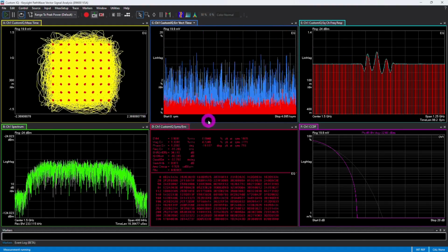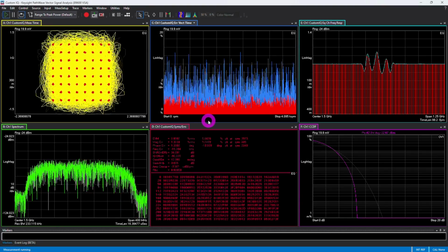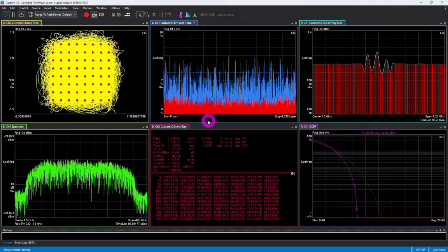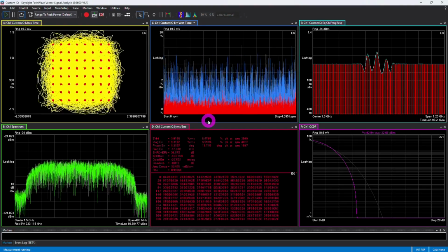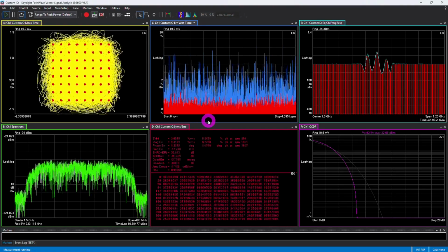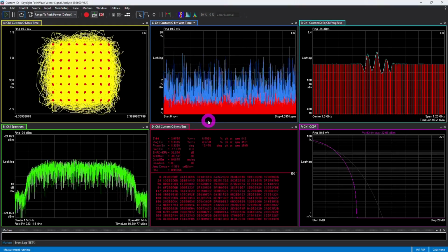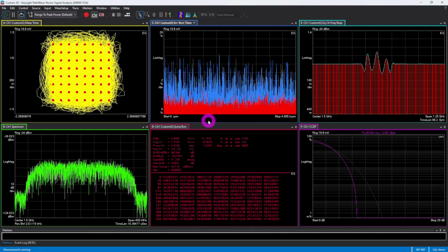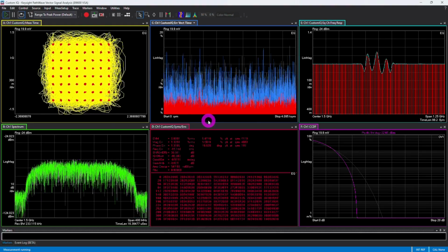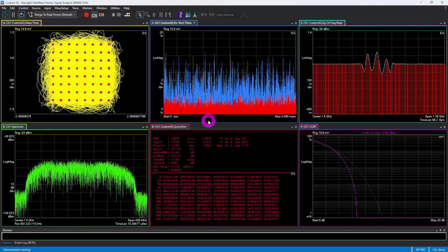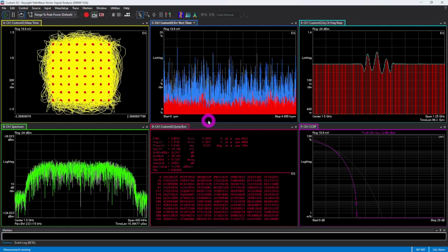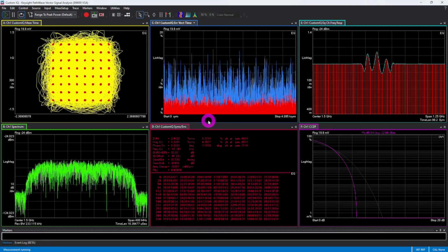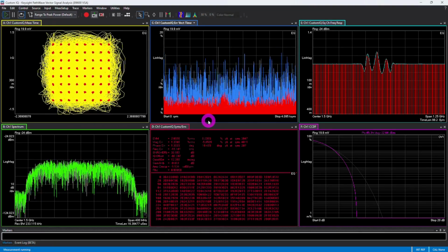So using the wideband IF, I can use any digitizer outside of the SM435 to digitize up to 800 megahertz of bandwidth anywhere in the band. That's quite powerful, which means that we're not directly limited by its internal bandwidth anymore. We can use other available instruments in the lab. The Keysight MXR has a lot of capabilities. It also has a real-time spectrum analyzer, as I mentioned, but there are other very powerful oscilloscopes that can be used to enhance the capability of the SM435. Now let's take a look at the Tektronix one, which also has some nice tricks up its sleeve.